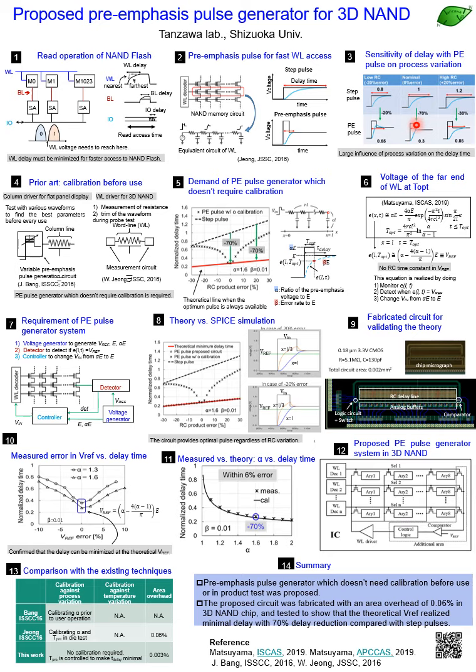In this example, you can get 70% word line delay time reduction in case of 0 RC time constant variation, whereas when your word line RC time constant varies plus minus 20%, the word line delay time reduction is estimated at minus 30% or minus 20% for each case.